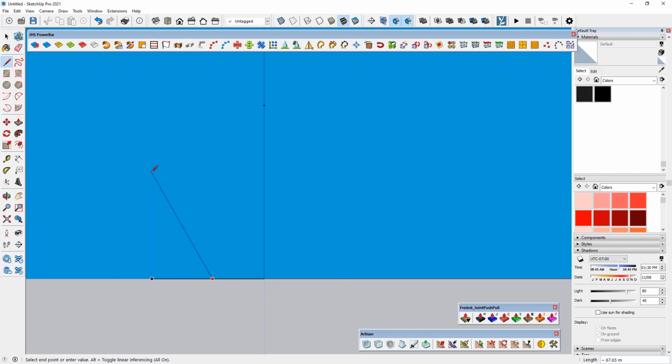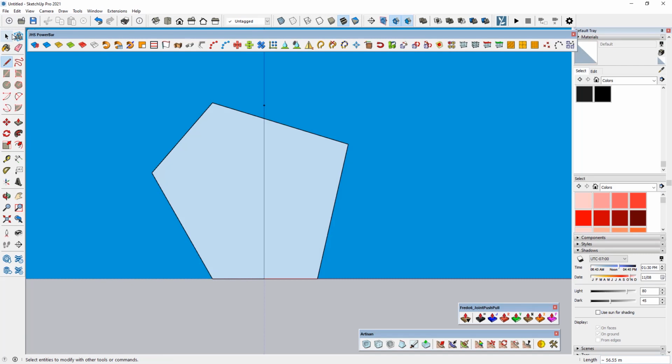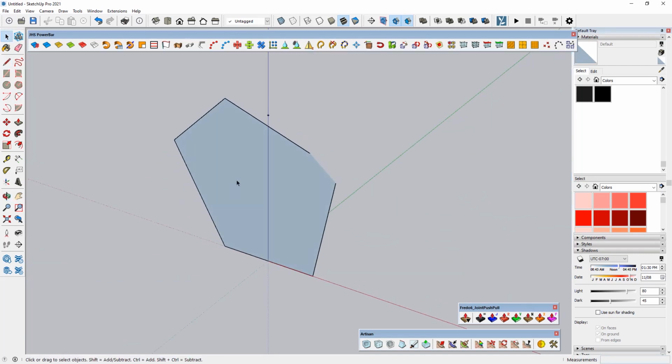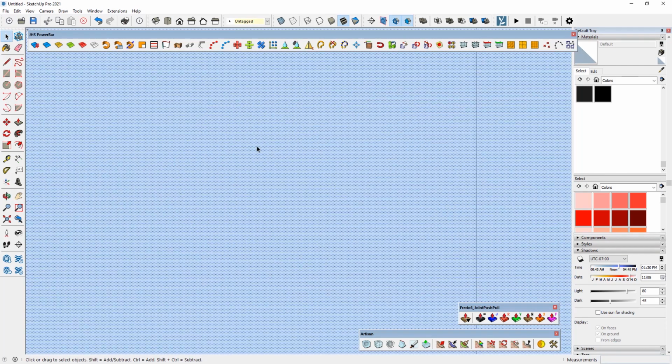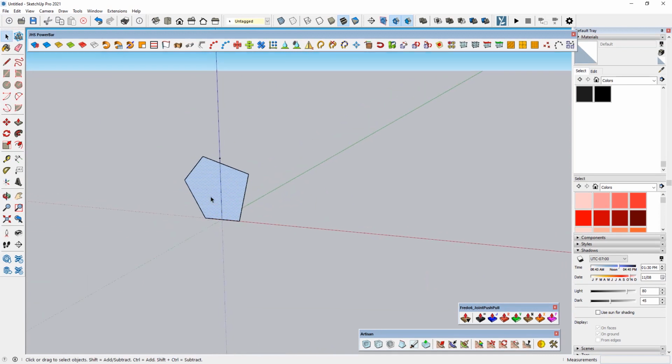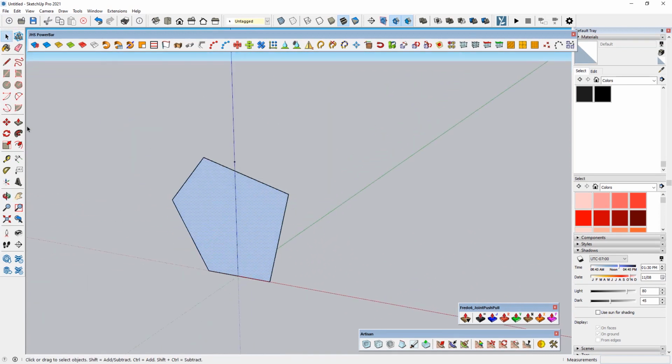And so we will start with the ground, and then we will add some basic shapes, something like this. Then we need to remove the bottom line, because I would like to have the one curve. And we have a surface. We can add push-pull for this surface to add the thickness.